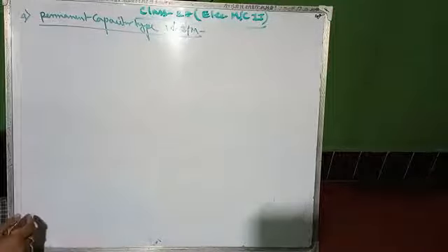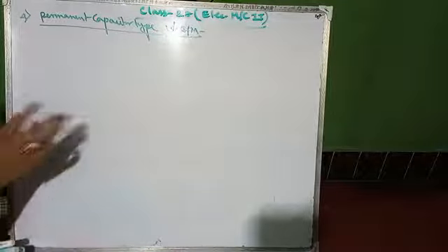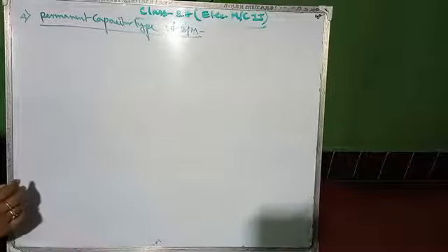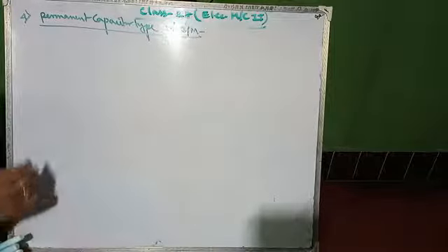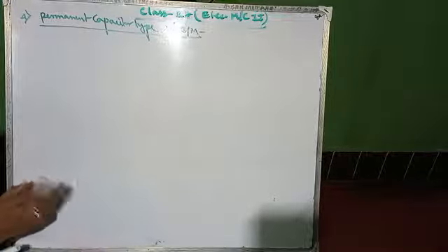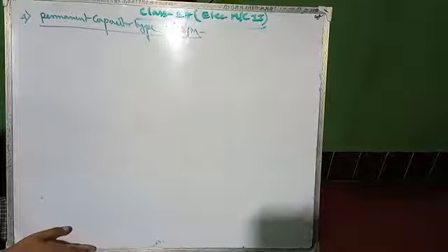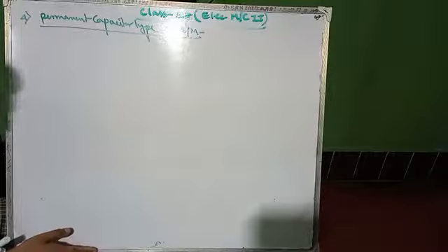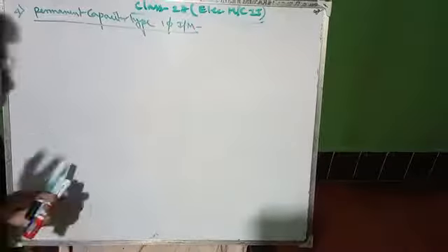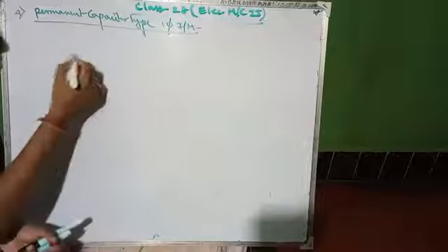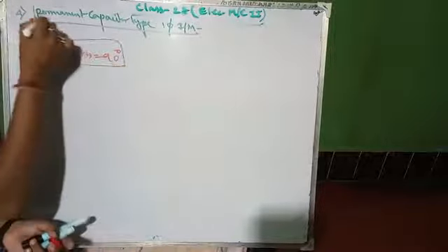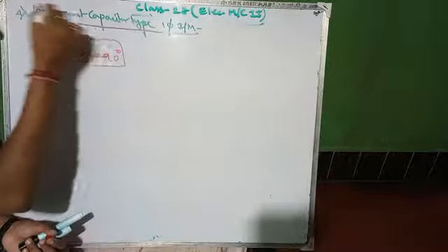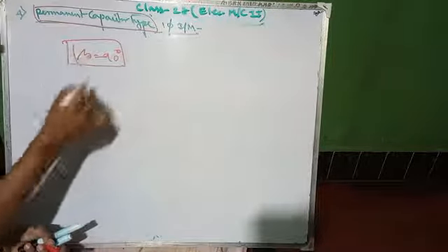At a particular desired load, the capacitor and the auxiliary winding can be so designed as to result in 90-degree time phase displacement between the two winding currents. That is it. This concept is very much important. For this case, beta equals 90°. That's why it is taken as the highest efficient type motor. A permanent capacitor type motor always has beta equals 90°.